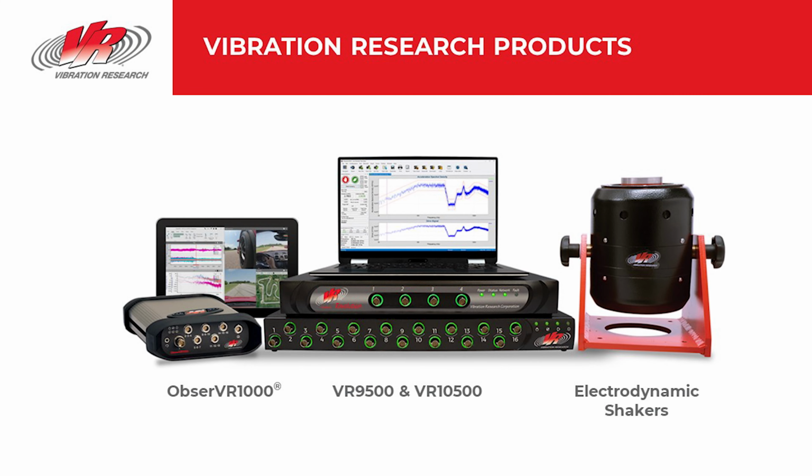Vibration Research designs and manufactures vibration control and data acquisition systems for vibration testing on any electrodynamic or servohydraulic shakers. The 9500 that we have here is the best-selling control hardware for vibration and shock testing. It's scalable up to 128 channels and features sample rates that include up to 200 kilohertz and 2 outputs for this piece of hardware. The 10500 is our high channel count control hardware for vibration and shock testing.